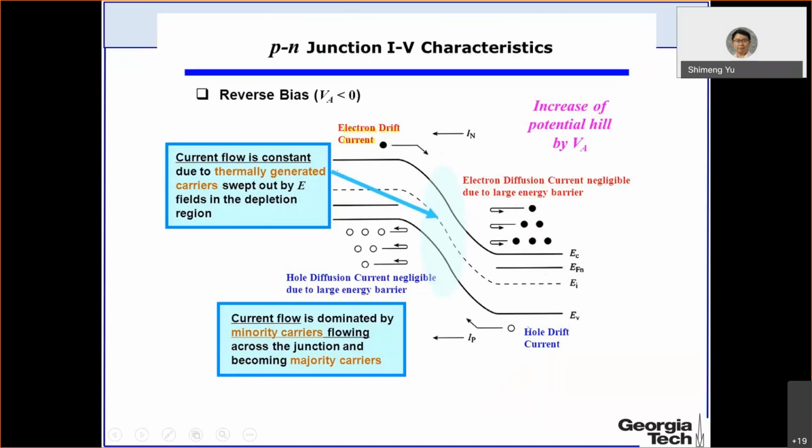So that's why, if you recall the IV towards the negative side, the current tends to approach a constant current. That means all the electrons available here will be swept to the other side by the drift. But you don't have more electrons here, so the current will not further increase. So the current will approach this negative I0. Similarly, you can argue for the holes.